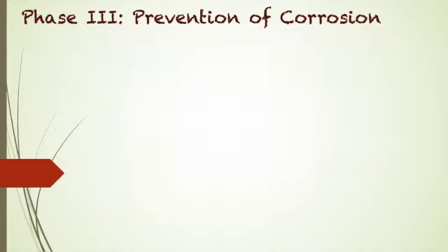The third method to prevent corrosion or protect the metal against corrosion is the cathodic protection. We also call this electrochemical protection. Okay, we know that in the corrosion reaction, the metal gets oxidized at the anode, and at the cathode, if it is acidic medium, the H plus ions accept the electrons and get converted to H2. So from these reactions, we can make it clear that forcing the metal to behave like a cathode is the principle of cathodic protection.